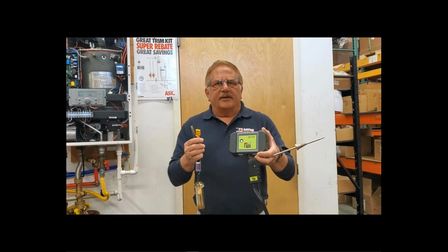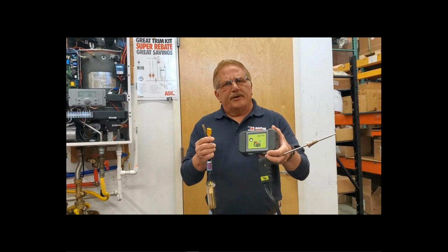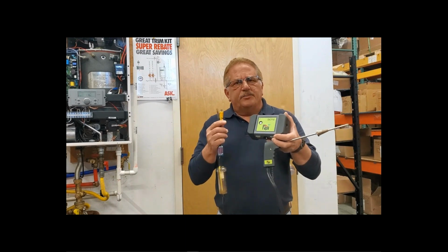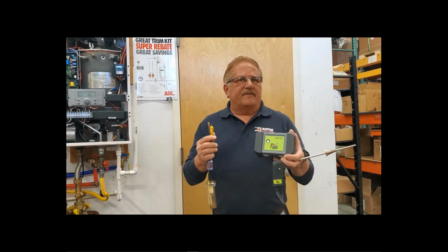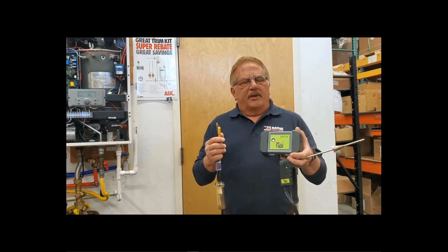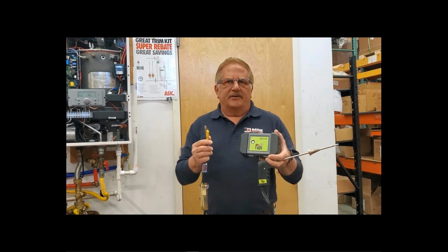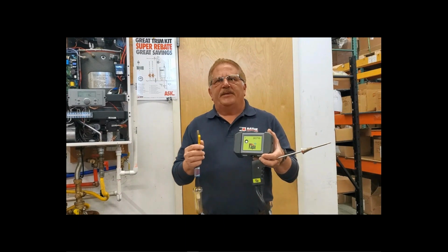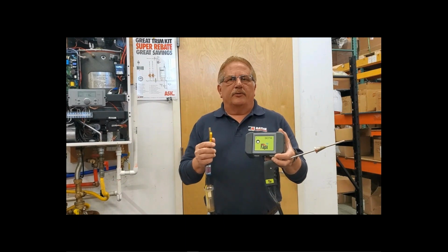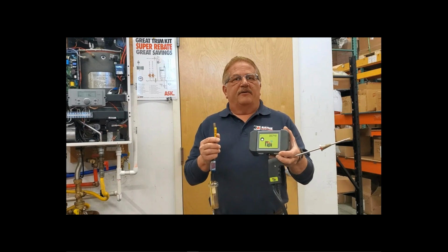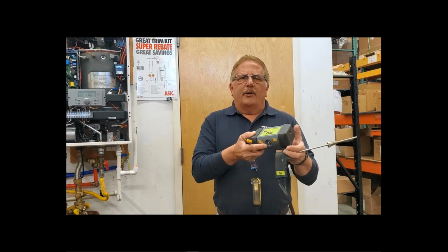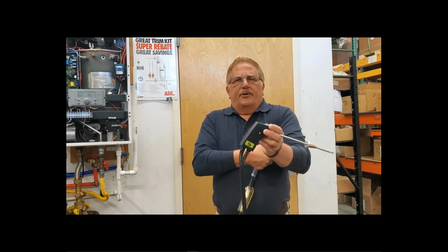We're getting ready to go ahead and start a combustion analysis, but prior to that, according to the manufacturer's instructions and directions, we should be doing a proper pre-purge of our test equipment. Many manufacturers require this. TPI is one of those manufacturers. Doing that pre-purge, it should not be done in the mechanical room or in the boiler room. It should be done in a fresh air environment. So we've already completed that pre-purge, and now we're going to go ahead and hook up our sample probe.